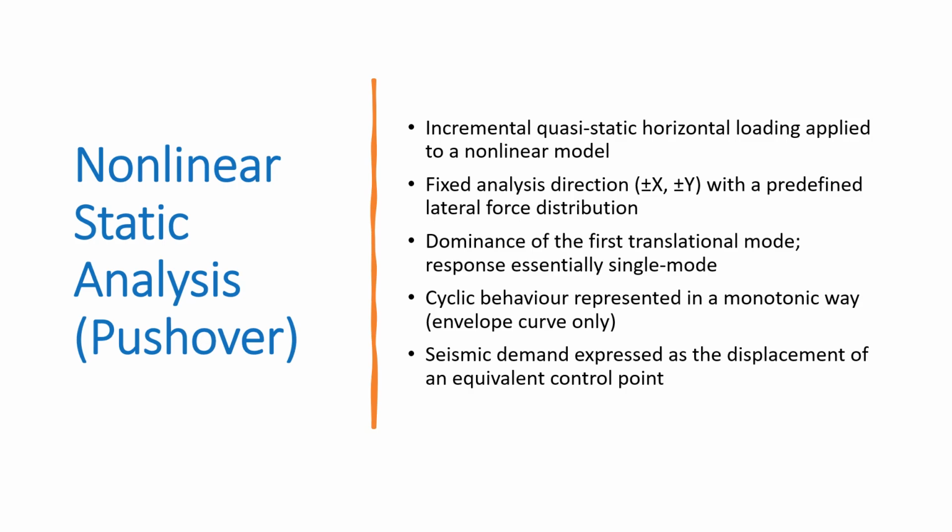You are comparing a linear response of a highly nonlinear behavior, which can be very different from structure to structure. These significant advantages of pushover analysis are there, but there are also some limitations for this kind of analysis.